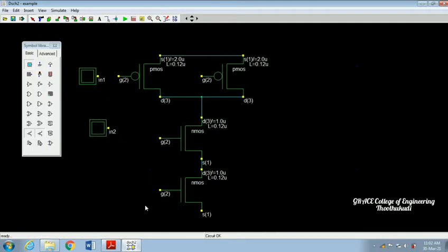For the CMOS construction of our NAND gate, we need to combine a PMOS and an NMOS together to give us input 1. Also for our other input we need to do the same concept. For that I have to connect both the inputs of our first PMOS and our last NMOS. With this connection I am going to connect input 1, and after that I am going to connect PMOS 2 with the NMOS gate.